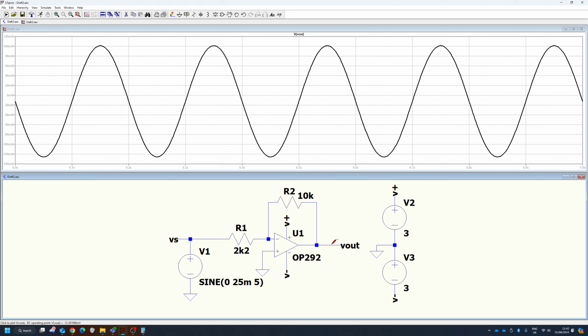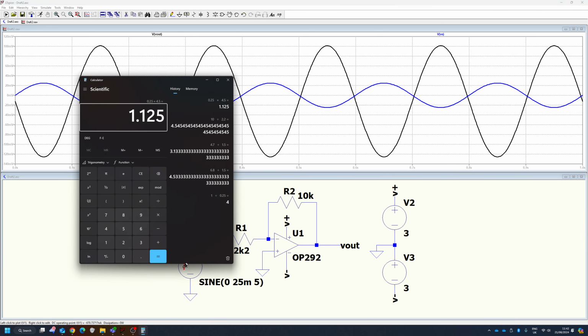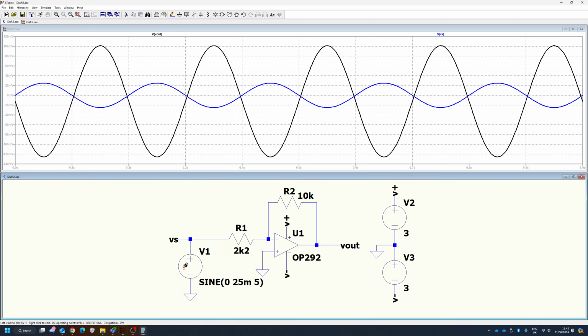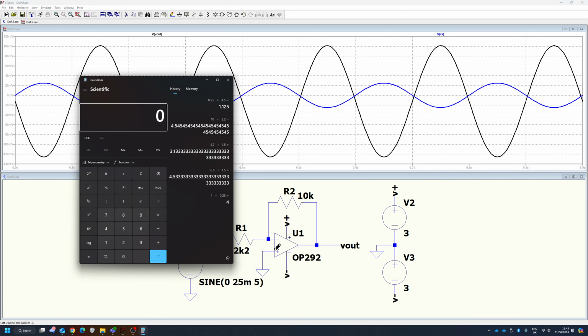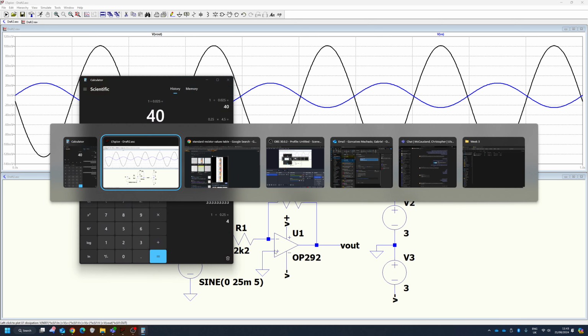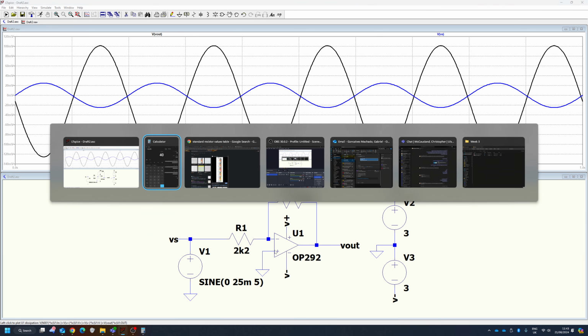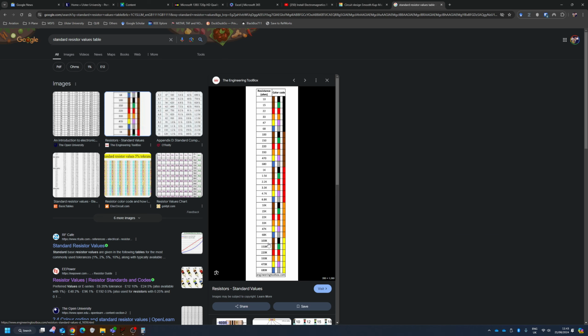Something wrong here, but all right. And my VS, all right, 25 milli. So, oh, sorry, 0.025. That is my mistake. That is my bad. I'm sorry. Times, yeah, that is correct. So we need more gain. So if I want 1 volt on the output and I divide by 0.025, that is 40. So I actually need here maybe 100K, right?